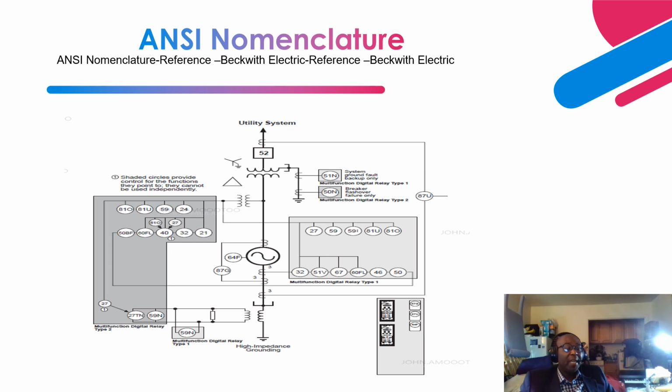So we have the 81O, like I indicated. This relay operates based on over frequency of the generator, when the turbine generator is operating in an over frequency condition. And what is an over frequency condition? Let's say the generator has a nominal operating frequency, like 60 hertz. The manufacturer will allow you to go beyond that.